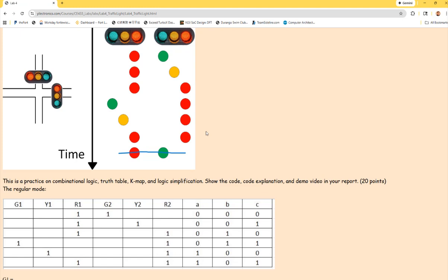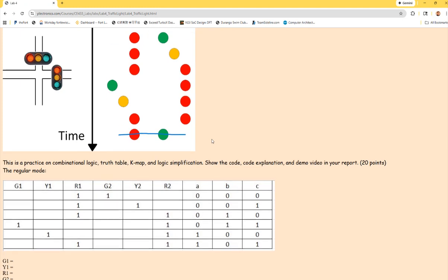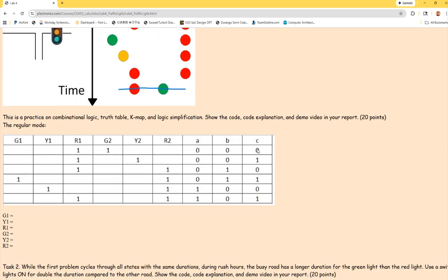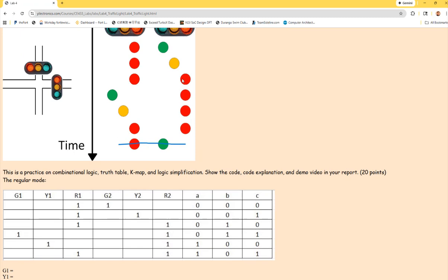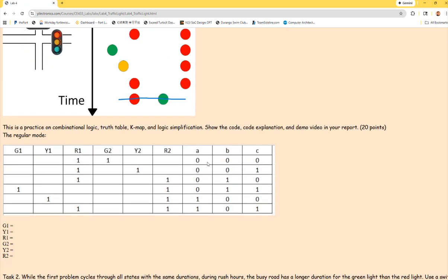So you only need 3 binary inputs for the decoder, because it gives you 8 combinations and you only need 6. It starts from 000 to 001 to 010 until 101, which is 5. So from 0 to 5, you get 6 states. When you cycle through all the states, you could simply add a 1 to this input.